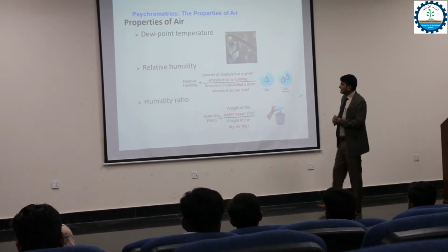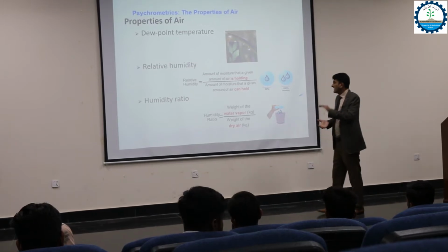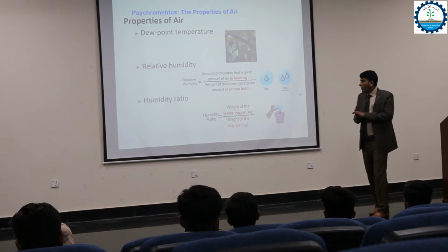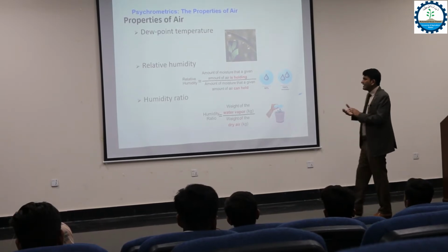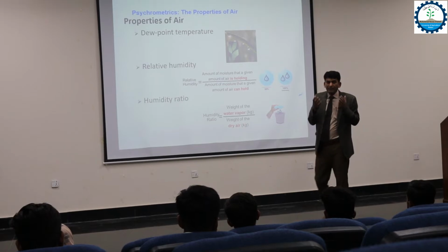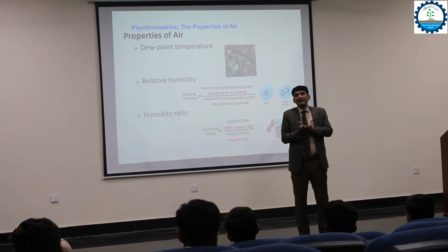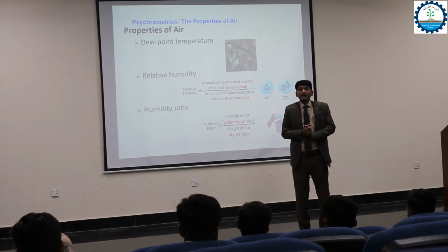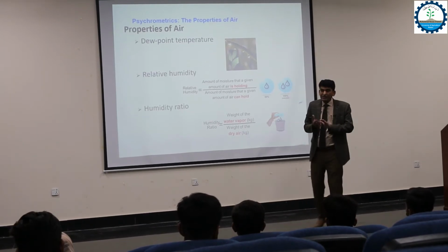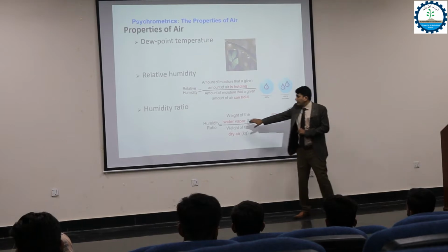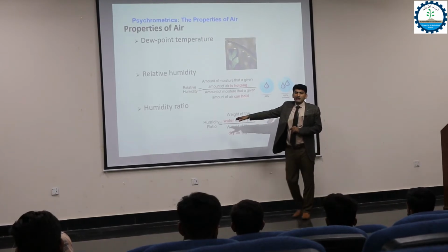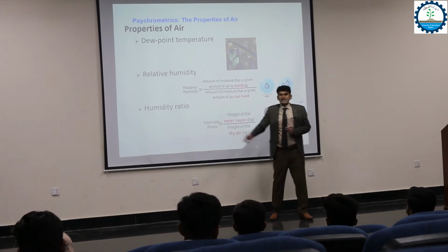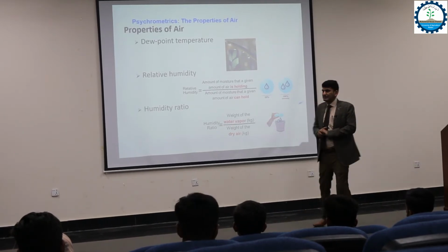So next, the humidity ratio. This is actually the weight ratio of the water vapors to the dry air. How much water vapor is in the air compared to the whole weight of the dry air. So the comparison by weight is the humidity ratio, or the second name we also mention, used in some books, is the specific humidity. So both are the same. Never confuse them in your next slides. Okay.